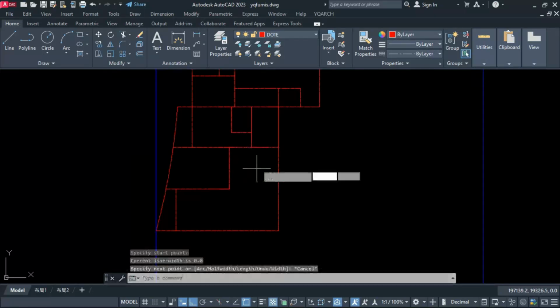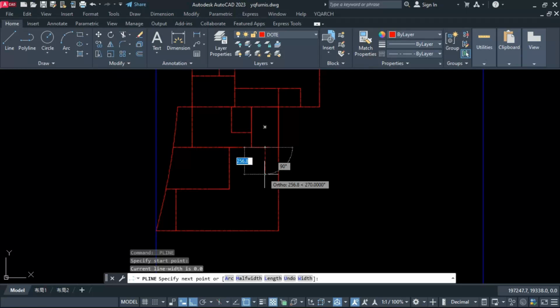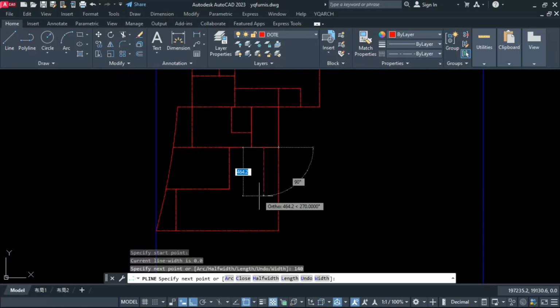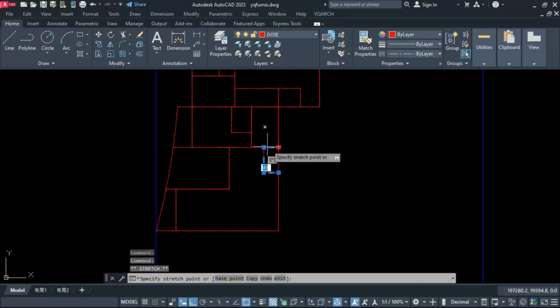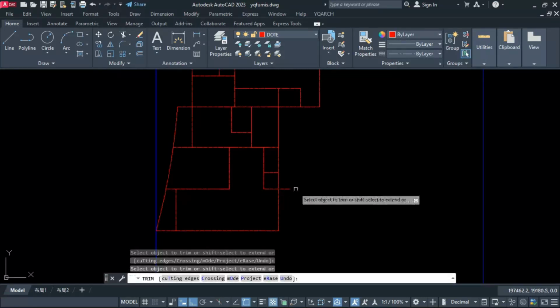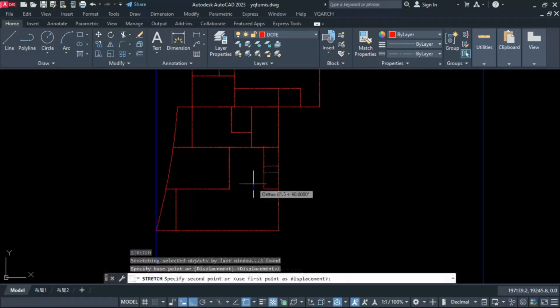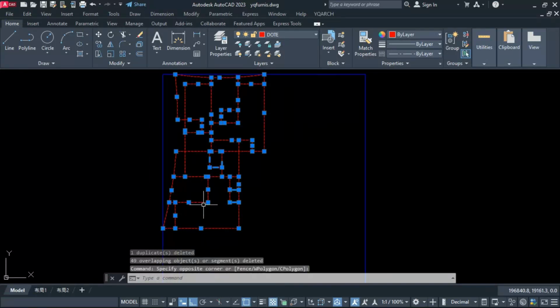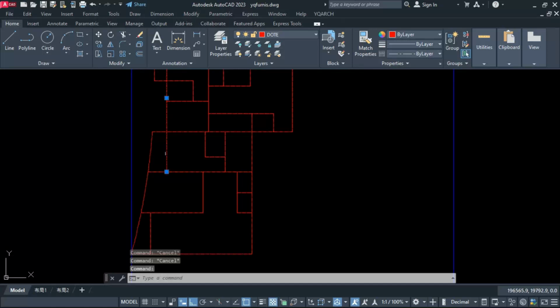Okay. Let this straight line from here, and we'll keep here. This is okay. 127 we are getting. More than that, you can keep 90 centimeter. Let this here 140. Down, we'll keep 240. And let this here. This is okay. For this apartment, we are getting wider space. Take this straight line, something here. Duct we are getting, common toilet and kitchen. Okay. Minimum condition we are covering for standard flat apartment.